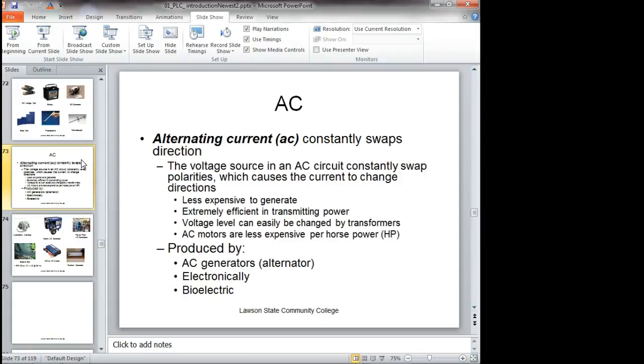If I've got a generator and I turn on my lights in my car, it would cause the voltage to drop down, but your regulator senses that and puts more current into the magnet, right? You understand? It causes the balance. You turn your air conditioner on, you roll the windows up and down. If you put a voltmeter on your battery, which is being charged, it stays almost constant because we have the ability to regulate.